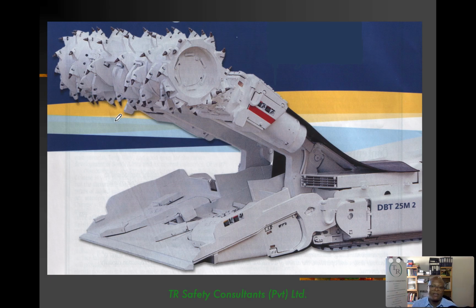Please take a look at the coal mining video clip that I have put in the folder as well. It will show you these machines in operation. The coal drops on the tray here, and with this arm and this arm, what we call gathering arms, they are pulling the coal towards the back, where inside here there is an armored conveyor belt that goes right out through to the back. At the back there will be a shuttle car parked, being loaded by the armored conveyor belt. So it's going back and forth. It's always behind the continuous miner. As it is filled, it goes to the tip and comes back.